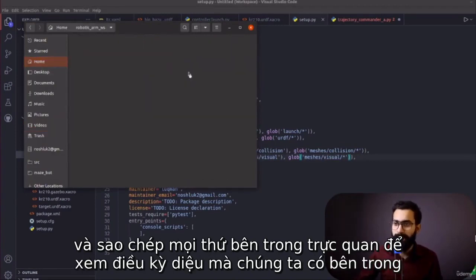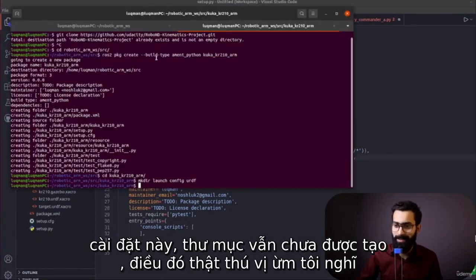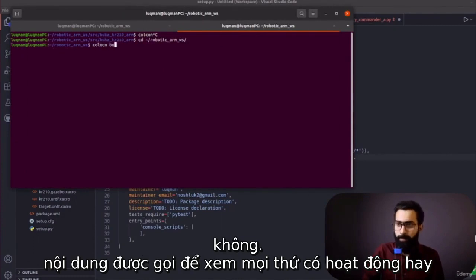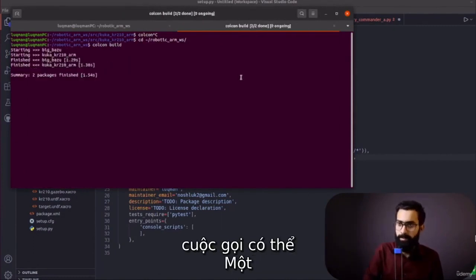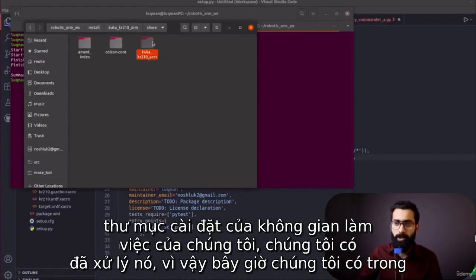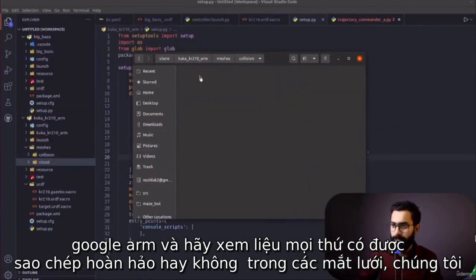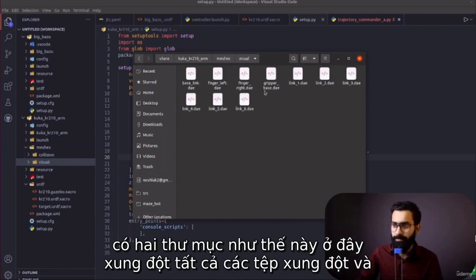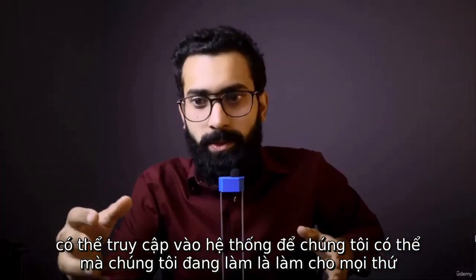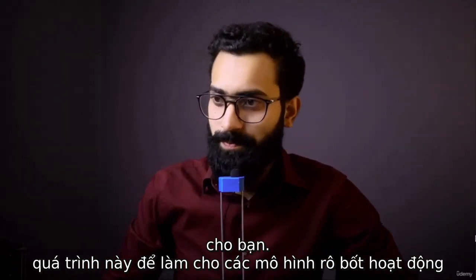To see the magic, we have to be inside of the share folder. What is actually happening? Robotic arm workspace install. The folder is not yet created. Okay, that is interesting. I think everything is fine. Let's perform colcon build to see if things are working or not, inside of the workspace root directory, which is this one. Colcon build. Let's see if it processes it or not. It has processed it. So now in the install folder of our workspace, in the share folder, we have KUKA ARM, and let's see if things are perfectly copied or not. In meshes, we have two folders, collision, with all of the collision files, and visual, with all of the visual DAE files. What we are doing is making things accessible to the system so we can produce a URDF. I know it is a little bit confusing, but you have to go through this process to make robot models work for you.